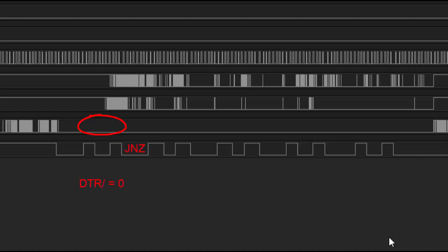So what this tells me is not only is the 8080 getting instructions off the bus, we saw that it was doing the interrupt enabled output like we told it to, but this tells me that the confidence test was able to reset and now give commands to the 8251 USART. So I know in fact that I am talking to the 8251 USART. That gives me more confidence that there's nothing wrong with the board up to the 8251.